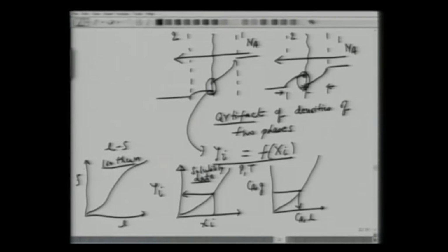So these are all used to determine the interfacial concentrations, which we say the two species are at equilibrium at the interface, although there is a concentration gradient within the bulk, within this film, giving diffusion flux. Okay, so if you understand this, now we can obtain expressions assuming a steady state.